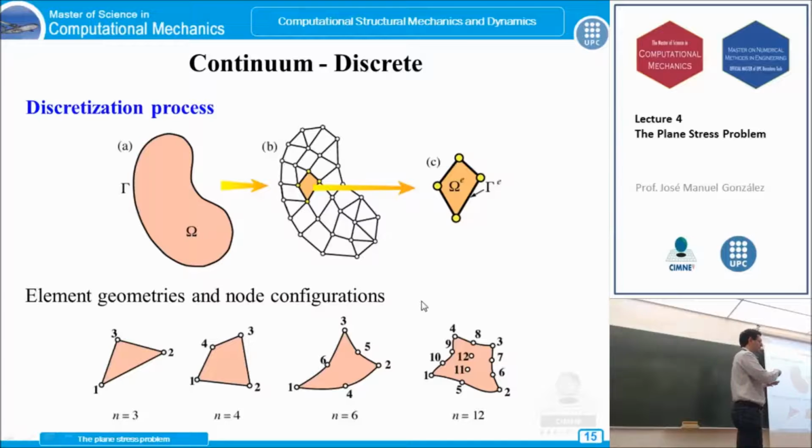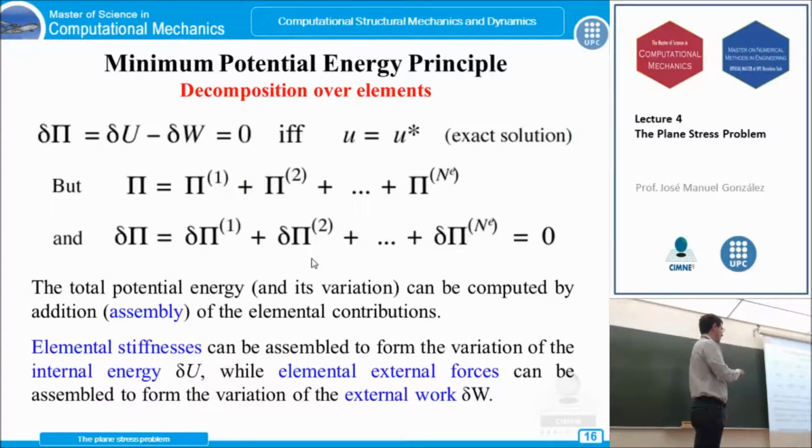This is a variational formulation for all the domain, and then we are going to worry about these elements. So this is general. This is not for one-dimensional element or two-dimensional. No, this is a general formulation. This is for the plane stress problem. So this plane stress problem could be solved choosing one of these plane elements, but this does not worry us now, because we're worried about this minimization of this total potential energy.